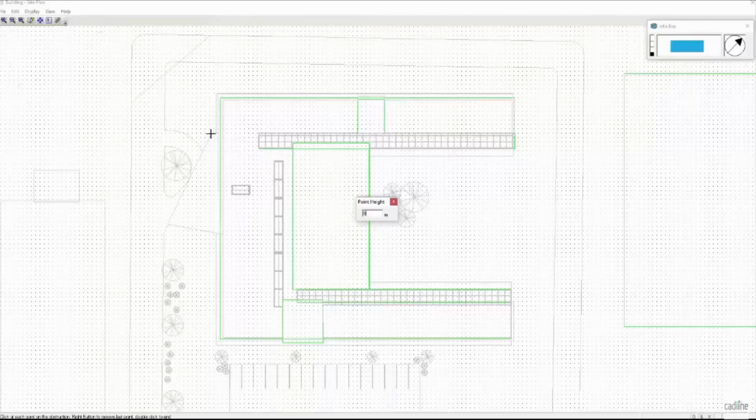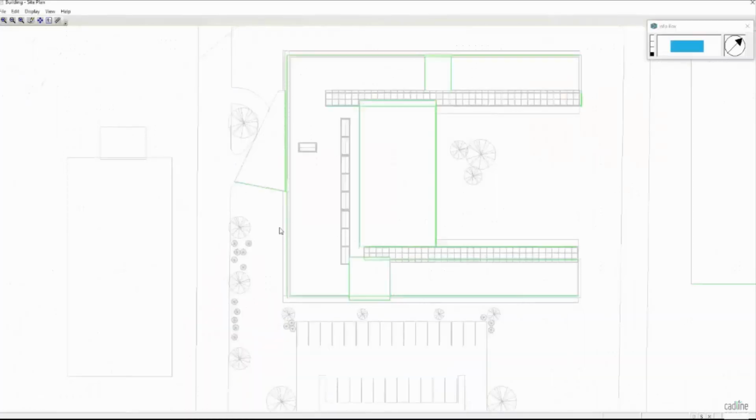So I'm going to make that 8 meters. I'm going to make that 8 meters. I'm then going to put the pitch on the angle and make that 12 meters. That's going to be 12 meters. Switching off my orthogonal so I can do the non-orthogonal line. That's it, 12 meters. Then we go back to 8 meters. Click on the start point. So that's created that shape.